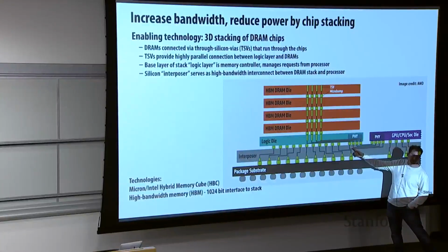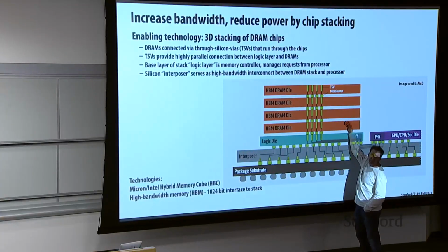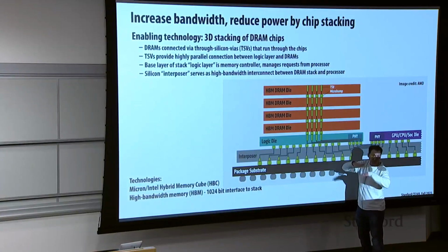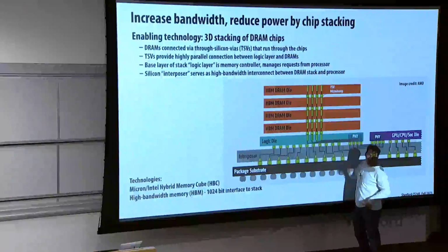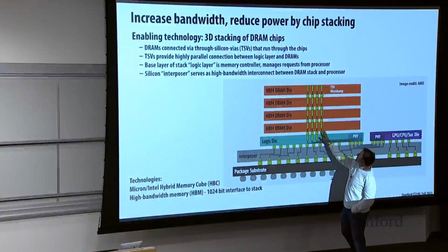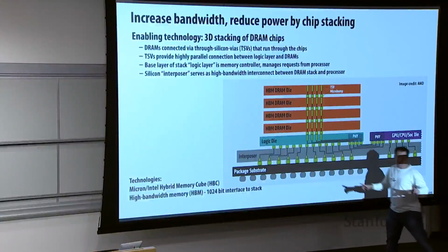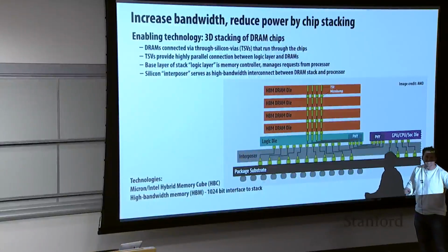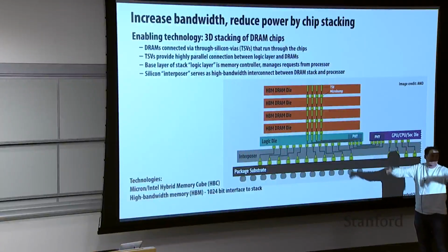They're not board traces. Okay, and then the DRAM chip is actually stacked, which means that these DRAM chips are on top of each other physically. The key technology was this thing called the TSV, through silicon via. You can think about the wires that used to be like 8 wires at the edge of the chip are now wires that leave the chip throughout the DRAM array.